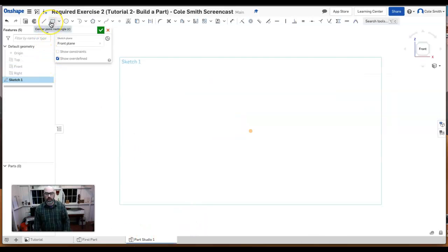I'm going to come up here and launch the rectangle command. There's a couple ways you can draw rectangles too. I'm going to do this first one as a center point rectangle. So when I click on, I get that origin showing up again. There's another thing I think I accidentally turned off called the origin. Turn it back on. It's just a little dot there at the origin point where x, y, and z equals 0, 0, 0. Kind of a nice place to start your drawing.